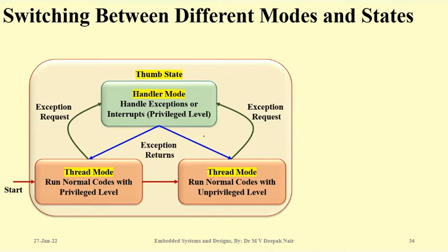Apart from that, it is also possible that you can pause your system and enter into debug state. Debug state means stop running the microcontroller, pause the operation, and check whether your program is running in a correct way or not.